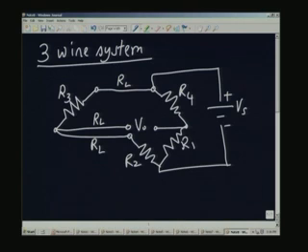So, by the arrangement like this, what has happened is, if you look at this R L is added to R 2, this R L is added to R 2, because I am measuring the imbalance voltage between this point and this point. If you want, you can call it A B. Imbalance voltage is measured across A B. So, if you look at this arm, actually it is R 2 plus R L, and if you look at this arm, this is R 3 plus R L. Therefore, I am adding a common value of resistance to these 2 sides, and therefore, if I look at the balance equation, let us see what happens.